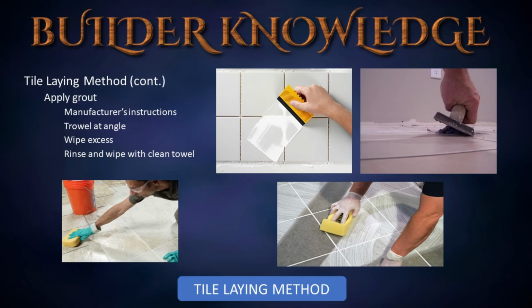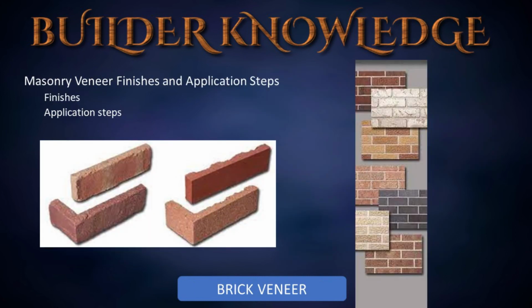After our tiles are laid and the adhesive has dried, we can apply our grout. Follow manufacturer's mixing instructions closely. Work rubber surfaced trowel in an arc, holding it at an angle so that grout is forced into the spaces between the tiles. Wipe excess grout from tiles with a damp rag. After grout is thoroughly dry, rinse the area and wipe with a clean towel. You will need to keep your tile clean and not allow the grout to dry on your tiles as it may stain. Next, let's talk about masonry veneer finishes and application steps.